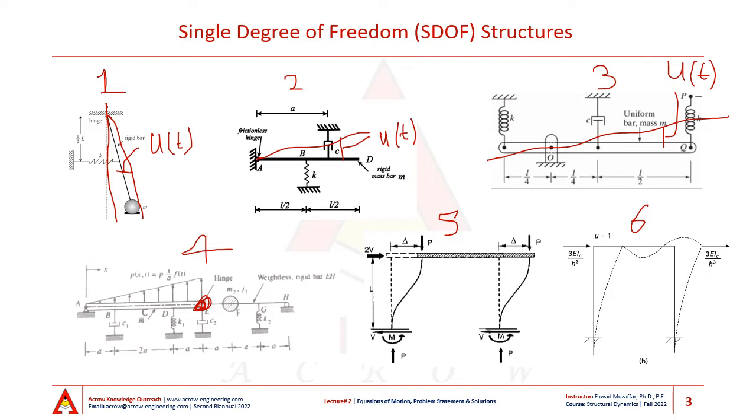So the question again is, how many degrees of freedom do we need to have to completely describe the deformed shape of this bar? And we can easily see that if I'm trying to draw a triangle here with a hinge over here, all I need to know is the position of one of the points, either at the hinge or along one of the beams, as a function of time t on these bars.